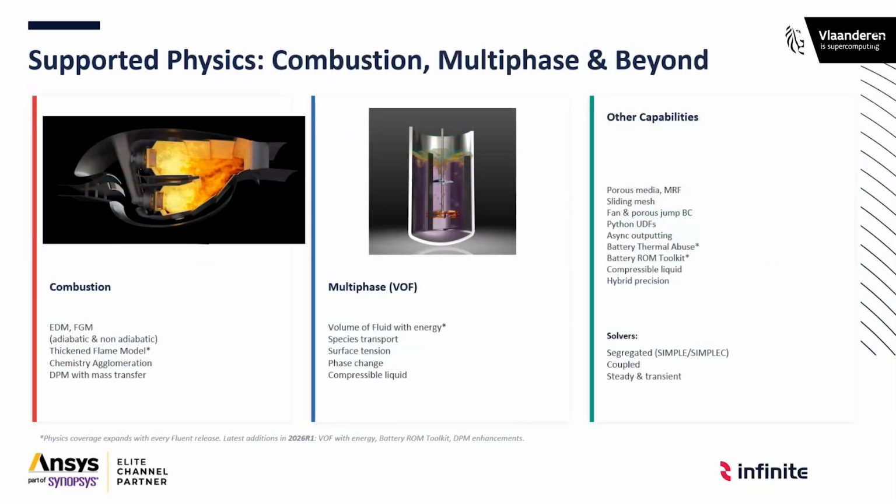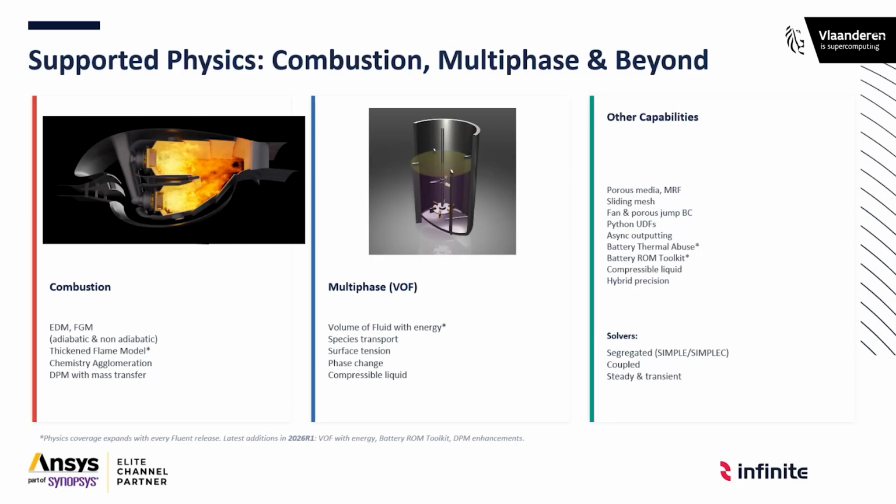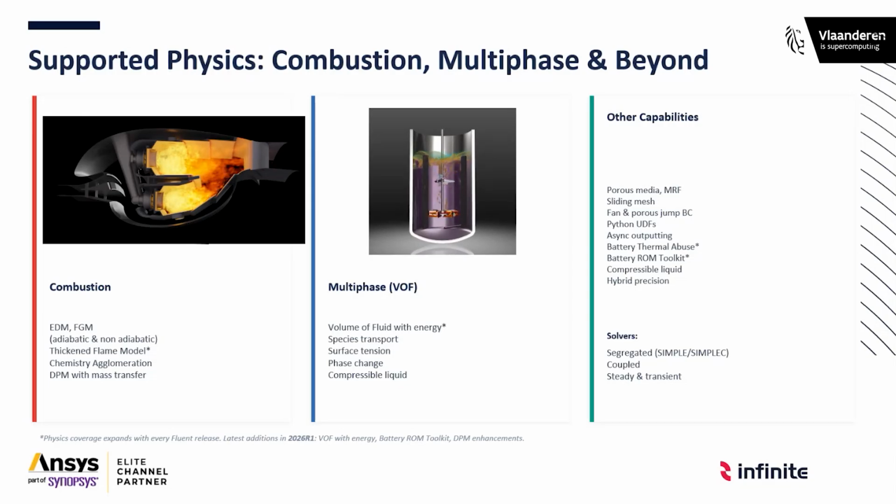In terms of combustion and multiphase, the eddy dissipation model and flamelet generated model are available both in adiabatic as non-adiabatic flame. In this 2026 R1, which was released beginning of March, the thickened flame model was added together with the chemistry agglomeration.